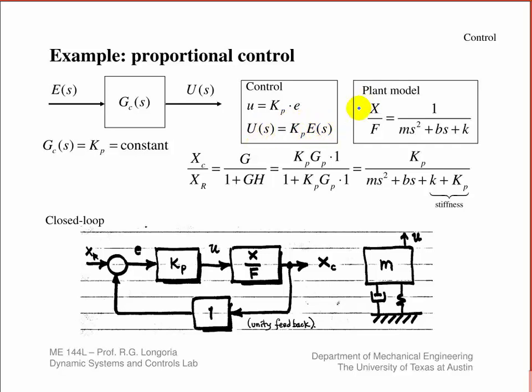If you insert that into that closed loop transfer function, say you don't have any disturbance. So here's a basic closed loop control. Let's say you're trying to control the position of this mass, right? So this is, let's say, X of this mass here. So let's have a transfer function that relates the position of this mass to some force that's applied on this mass. Let's say that's not shown, but that's going to be the control action U. So X, the position of this mass, over U, the force on that mass, and that's what I'm applying there. So let's say I know this transfer function.